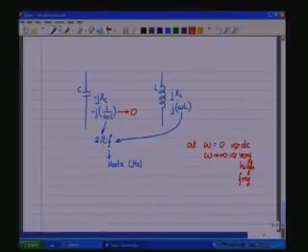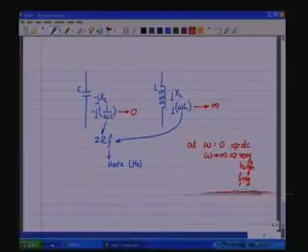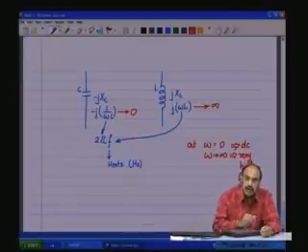At high frequencies the inductor gives a very high reactance, tending towards infinity, which means it tries to block high frequencies. So, it will drop across it all the high frequency, while the capacitor will pass all the high frequency components.